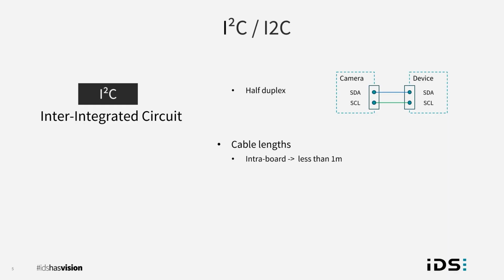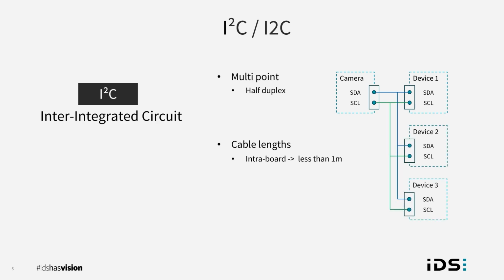The main advantage of I2C is that multiple devices are supported. This is achieved through addressing. We would send a message to control a specific device preceded by the address, so the specific device knows that a message is intended for it. All other devices connected would simply ignore the message. I2C does not require any intermediate level adjustments and is designed for connecting devices on a network.